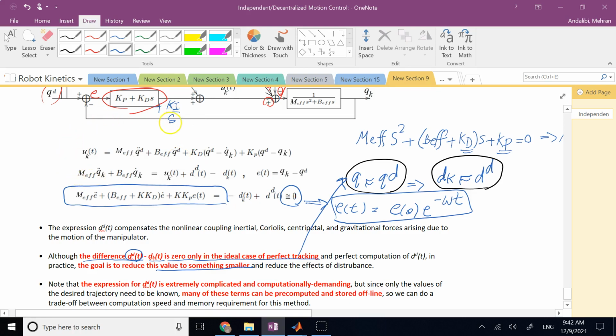But in practice, when the steady state errors that are non-zero show up in my system, I always try to add an integrative component, of course with not really large gains, because large gains of integral component will always lead to instability of the system. So that's one reason, one thing we need to discuss.